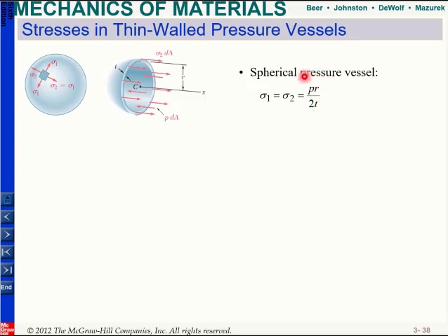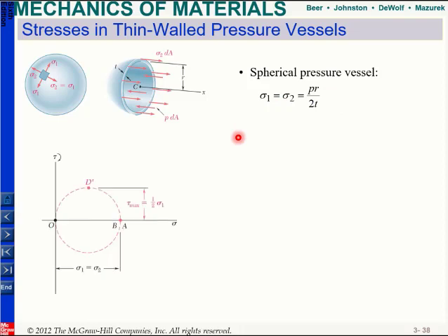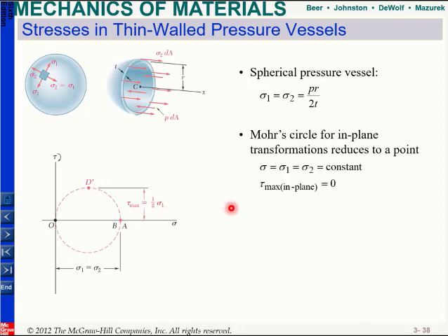Okay? And if I ask you to draw the Mohr circle of this one, how would you draw it? Since there is no shear, I know that these are my principal stresses. If you plot it, basically what you will get is just this point. And since this is plane stress, my third principal stress is 0, so I will get this Mohr circle. If I ask you what's your maximum shear stress, it's equal to 1/2 of your normal stress.